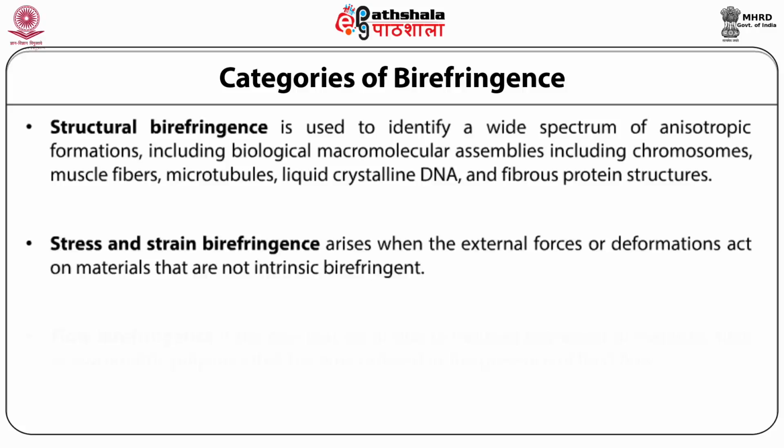Birefringence can be induced by inhomogeneous mechanical stress. This can be observed by placing a piece of acrylic between two crossed polarizers and applying stress to the acrylic. Colored patterns can be observed resulting from the wavelength dependent effect of stress induced birefringence.